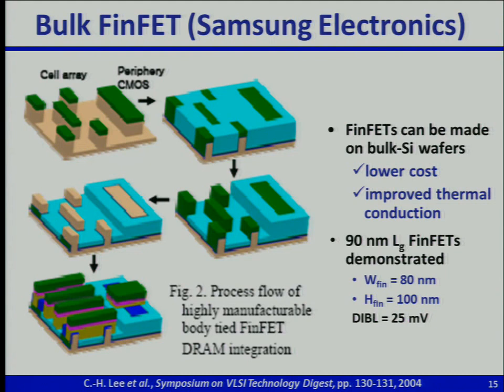So on the left sort of illustrates schematically the fabrication process. So in a CMOS process, you first define the regions where you're going to make the transistors. So that's here. And then you usually etch down the silicon and fill the regions in between the transistor regions with oxide. So it's insulating, right? This is the shallow trench isolation oxide that we talked about.